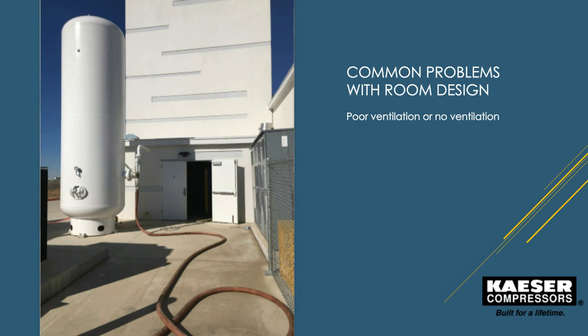We do see the double doors, so if those doors are closed, we probably have a severe negative pressure in the room as the compressors are trying to suck in all the air they possibly can to keep them cool. Now, the other thing with a room like this that has no ventilation means that we're probably going to be overheating these compressors, and we're going to see severe wear and tear on them, and the lifetime of the equipment is going to be reduced. We're going to have a little bit more on this particular site a few slides later, but if I told you we had 4 100 horsepower compressors with integral dryers in this room, I hope you would be as concerned as I was that we have no ventilation.